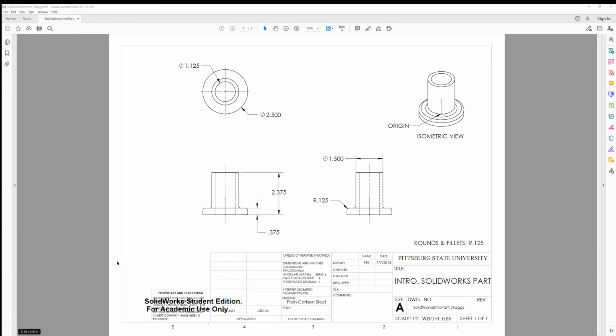So before we get into SolidWorks, let's talk a little bit about this drawing. This drawing is using orthographic projection, and that's what these three views here are. Basically, you're looking at it from what we'll call the front view in this region right here, and then if I looked from the top down, I would see this right here, and then if I looked from the right side, toward the left, if you will, where the part's in the middle, it'd be looking at right here. And we'll get into more detail as far as what all the different line types are, so that you're able to read these things much more naturally